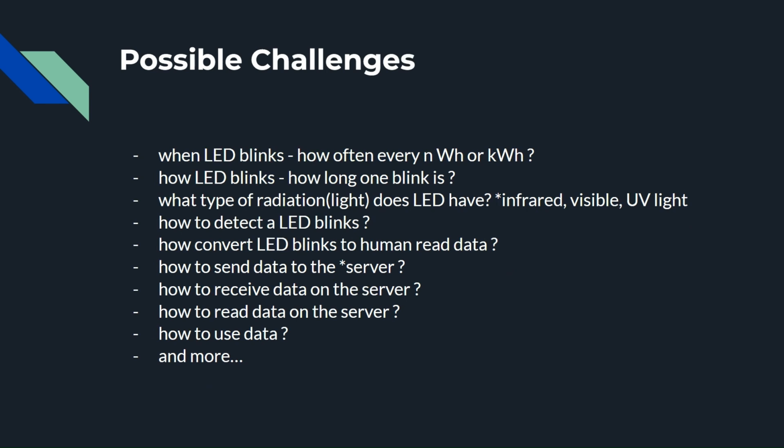If we would like to use that way, the possible challenges we may have are: when the LED blinks, I mean how often, every n watt hour or kilowatt hour it blinks, how the LED blinks, how long one blink is, what type of radiation, I mean light, the LED has, how to detect these LED blinks, how to convert LED blinks to human readable data, how to send this data to your server, how to receive data on the server, how to read data on the server again, and how to use data, and more and more. And to be honest, each of these challenges contains more challenges inside.